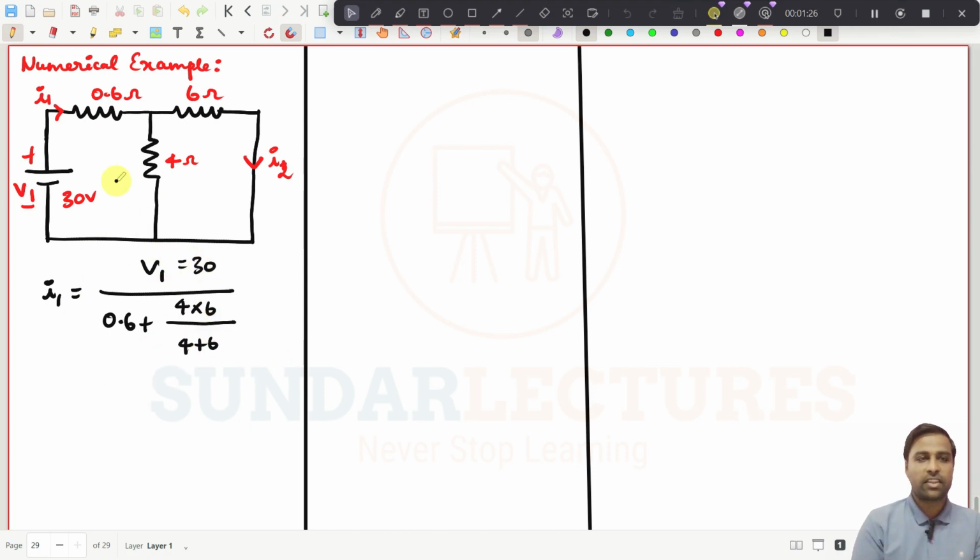If you simplify this, then you will obviously get the current flowing here. So if you simplify, you will get I1 equal to 10 amperes. You just simplify by yourself, obviously you will get the values. So this is the whole idea. This will be 10, right? It will be 24, so 24 by 10 you will get 2.4, 2.4 plus 0.6 will be 3, 30 by 3 will be 10 amperes. Okay, maybe we will do it by ourselves. Anyway, this current is 10 amperes now.